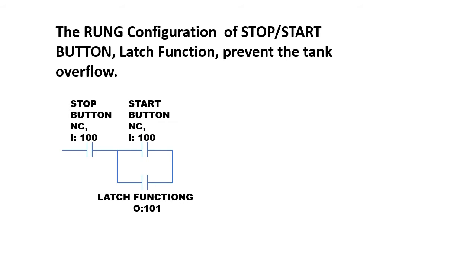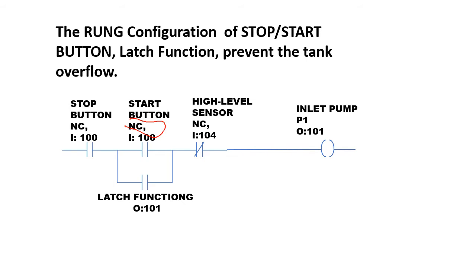This is a normal open. I get it, it is the wrong type. Below the start button sign is the latch function. This is how the latch function of a start button looks. Then the high level sensor, normal close.